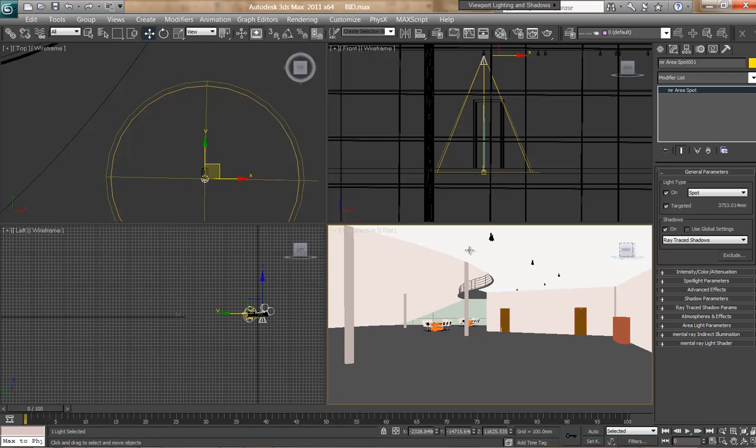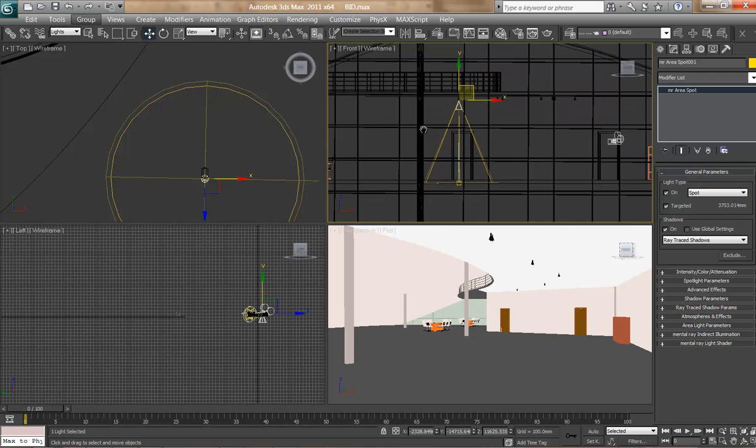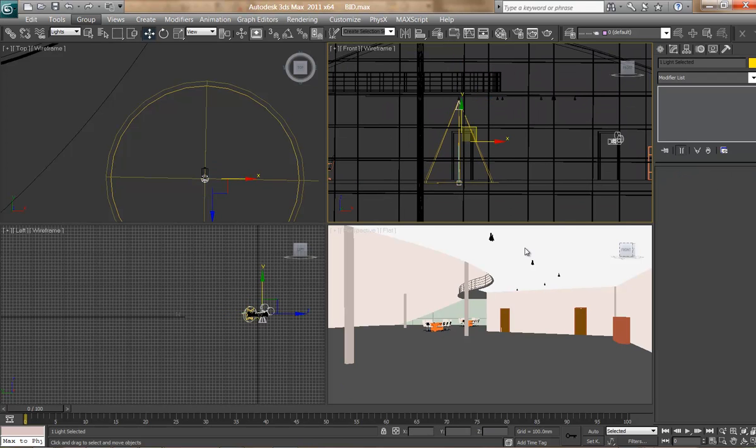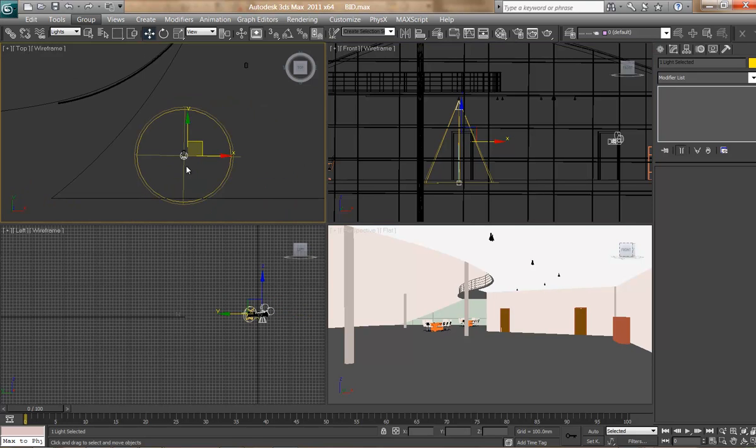Yeah, exactly, that's right. So I want to copy it for all these others. So I'll just change the filter up here. You can see this has got all. I'm going to change that to lights, and now I can make a window, and you can see it's telling me I've got one light selected, but I've got both the target and the light source. Just makes it easier to copy it. So I'm going to do a series of copies now.